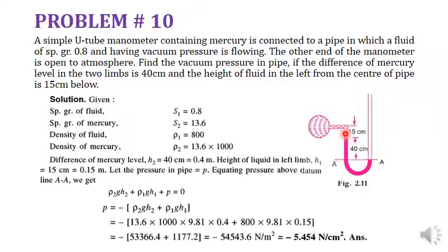The fluid in the pipe has a specific gravity equal to 0.8, so you need to determine the density by multiplying it with the density of the water. For this particular fluid, for which the negative pressures need to be determined, the value is given, that is 800. First of all, the specific gravity is given. The manometric fluid is mercury.